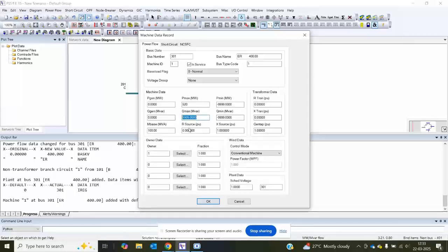So this is the reactive Q limit, which is around 200 MVAr, and there is a minimum reactive power limit of minus 200 MVAr. This is the maximum absorption the generator can do. Now there is a minimum turbine limit, specified as P min. Suppose this is 50% of the unit, so around 260 megawatt.